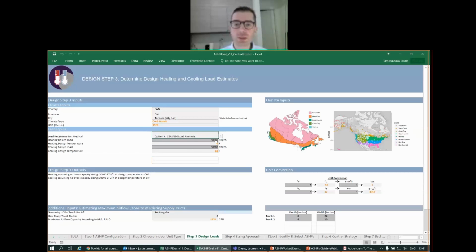If I have to stress one thing about this particular tab though, it's that load calculation, and appropriate load calculation, is extremely important. If you have a load calculation that's already oversized versus the true load of the building, that's likely going to lead to oversized heat pumps, which in turn can lead to issues like cycling and thermal comfort issues, which at the end of the day can result in more callbacks. And those are things that I think ideally everyone would like to avoid.